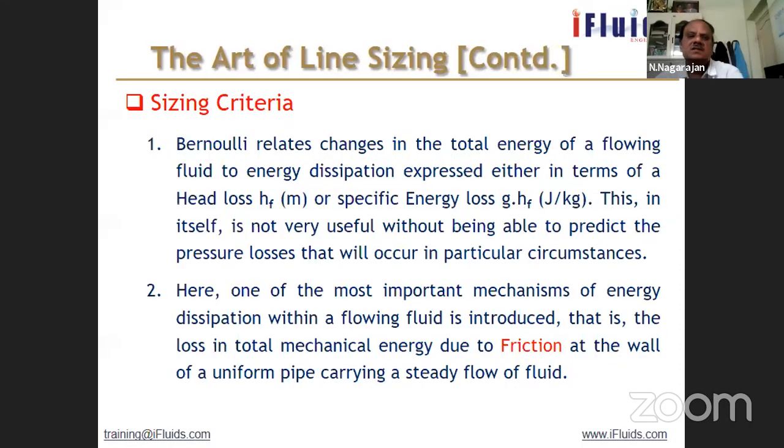So for sizing criteria, we use the velocity and pressure drop. These two are the important parameters in fluid flow. So the Bernoulli equation you all know: the total energy of a flowing fluid, with energy dissipation, is expressed in terms of a head loss. Okay. That we have seen in the picture earlier.